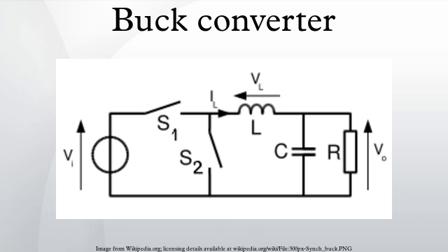It can be seen that the output voltage of a buck converter operating in discontinuous mode is much more complicated than its counterpart of the continuous mode. Furthermore, the output voltage is now a function not only of the input voltage and the duty cycle D, but also of the inductor value, the commutation period and the output current. From discontinuous to continuous mode.